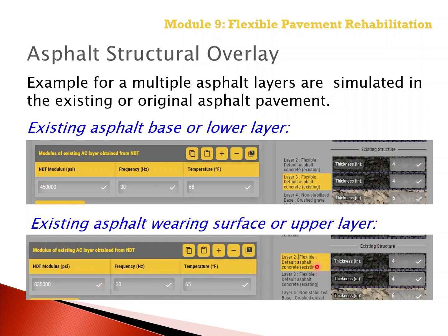They could include, for multiple asphalt overlays, the original pavement structure and then the asphalt overlay, assuming it's thick enough for the asphalt overlay, the existing asphalt overlay that was placed after the original pavement construction, especially if there's some reason why the two would exhibit significantly different load response differences or different stiffnesses.